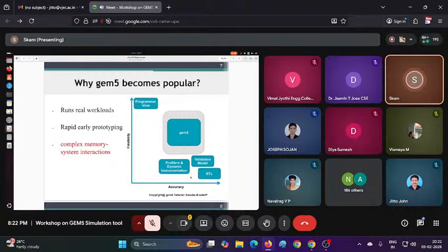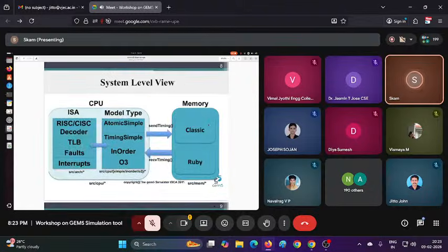If you can code your implementation, your cache replacement policy, or anything which you want to work in the processor, using RTL, that is the best option. But coding in RTL is not that easy. There comes the role of gem5, where you can generate output similar to your RTL implementation. That's why, accuracy wise as well as flexibility wise, you can see that gem5 plays a key role in the semiconductor industry.